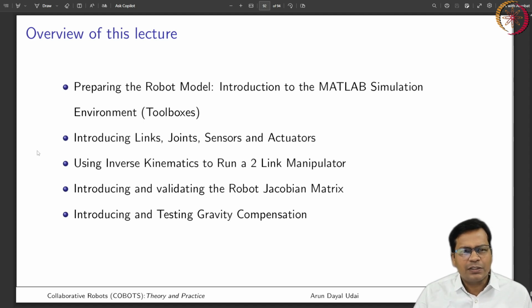I'll discuss how to introduce links, joints, sensors and actuators to the joints so that you can actuate the joints using torque, using motion. And you can sense the joint angles and joint torques. So I'll introduce you to all those blocks, how to introduce them, and run the simulator on a two-link manipulator.